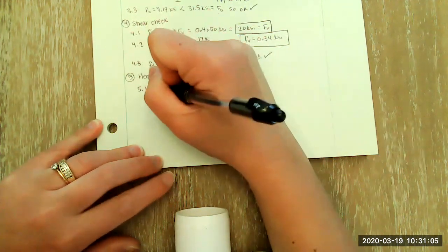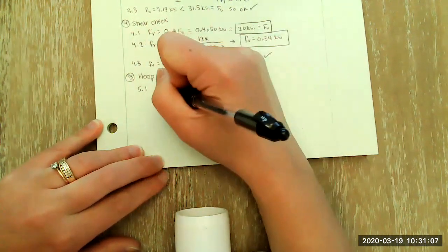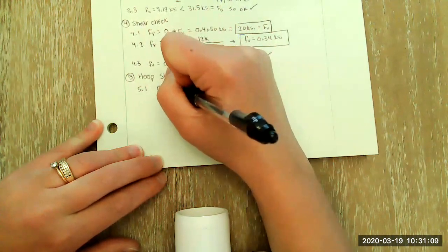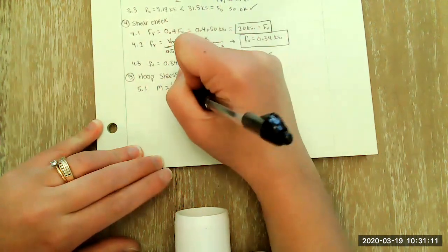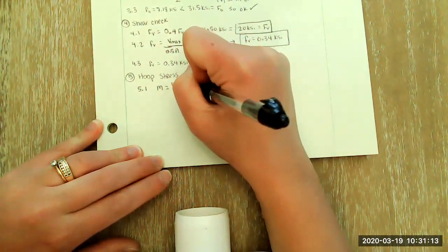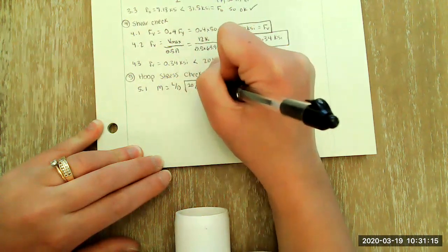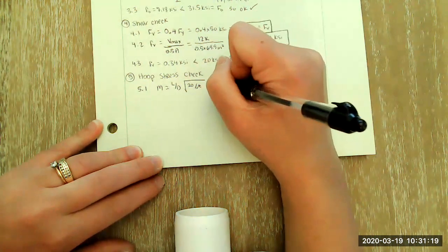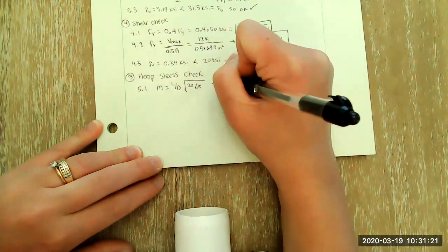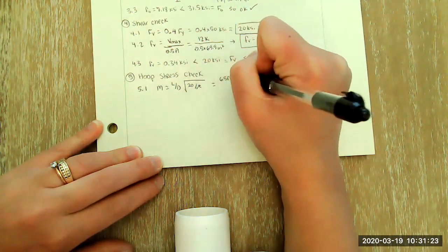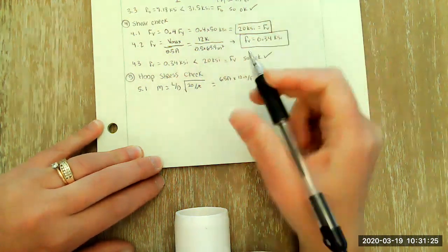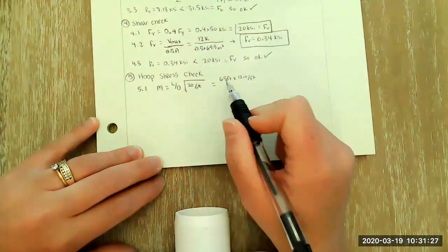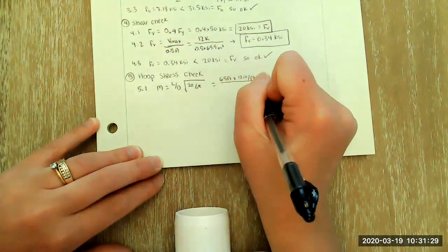So first we'll calculate our geometric shape parameter M, which is equal to L over D times the square root of 2D over T. Plugging in numbers and being careful with units, my total length of the pile is 65 feet times 12 inches per foot. Remember to use the length, not the effective length here.